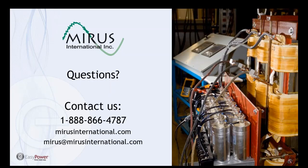There are rarely harmonics in the power system below the 5th, although many of you would say, well, what about the 3rd harmonic? Well, 3rd harmonic is present when there are single phase to neutral loads, and it's a zero sequence harmonic. So in applications where we're at the 480 volt level or 600 volt level, we rarely have single phase loads. So we rarely see 3rd harmonic.